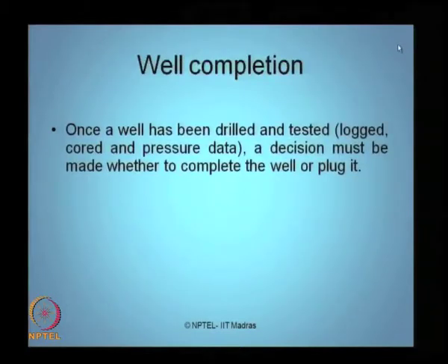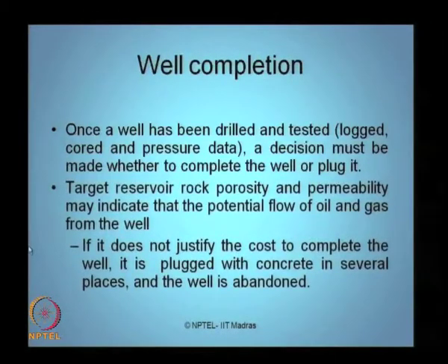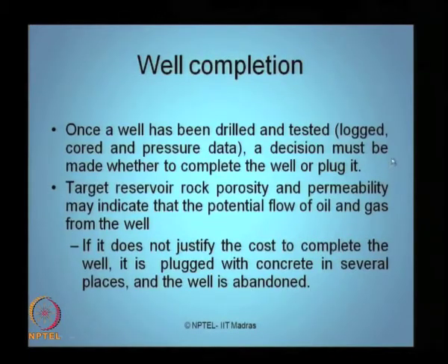What do we understand by well completion? Once the well has been drilled and tested, that is, logged, and core and pressure data obtained, a decision must be taken whether to complete the well or to plug it. So, what do we understand by well completion? The target reservoir rock porosity and permeability will indicate the possible potential flow of oil and gas present in the well. If it does not justify the cost to complete the well, then it is plugged with concrete in several places and the well is what we call abandoned.